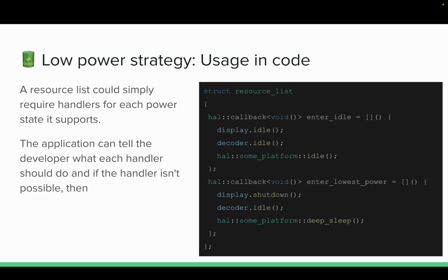And actually, there's a power saving mode that ARM Cortex devices just have. There's an instruction called wait for interrupt, and you could basically just call that function that puts the system effectively into a low power state, waiting for an interrupt to occur before it wakes back up. And that's pretty much the idea of how you'd use it. So to me, it seems relatively simple. You just give a callback for what's needed to power the thing down, and then any calls that end up powering back up, power it up.